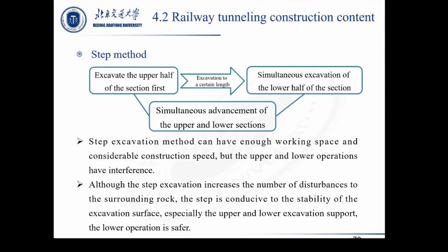The step method is a method of excavating the upper half of the section first and then exit the lower half of the section at the time after the excavation has reached a certain length. With the upper and lower half of section progresses.